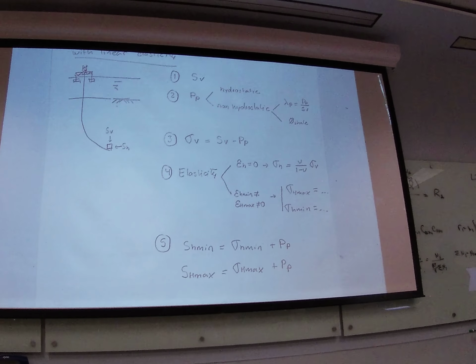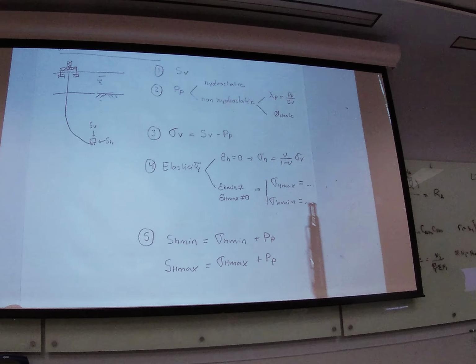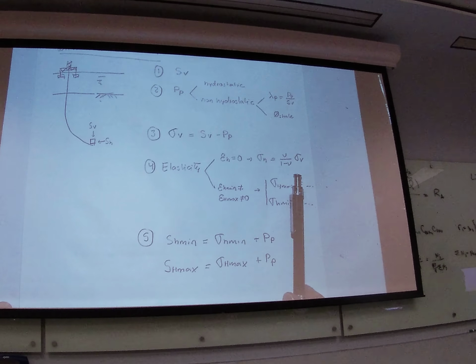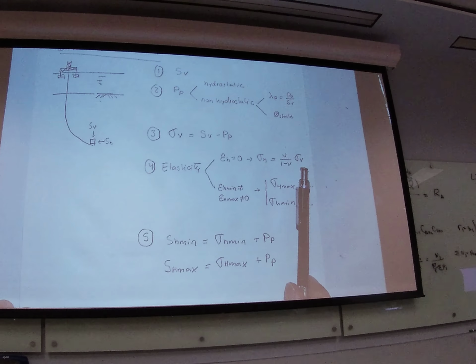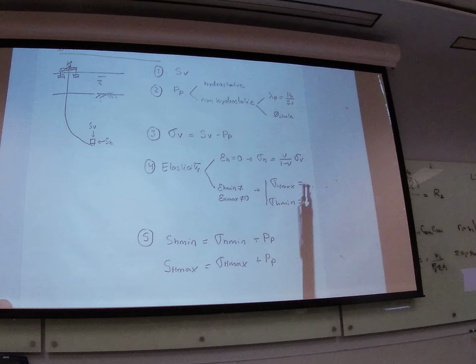Notice that you always apply the elasticity equations to effective stresses, not to total stresses. First, convert everything to effective stresses, and then you can calculate the total stresses.